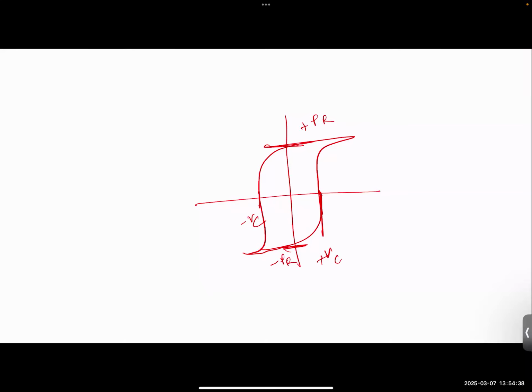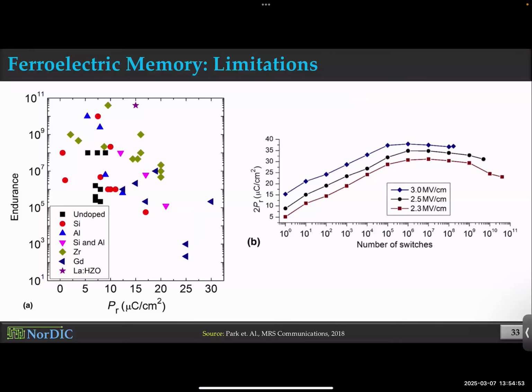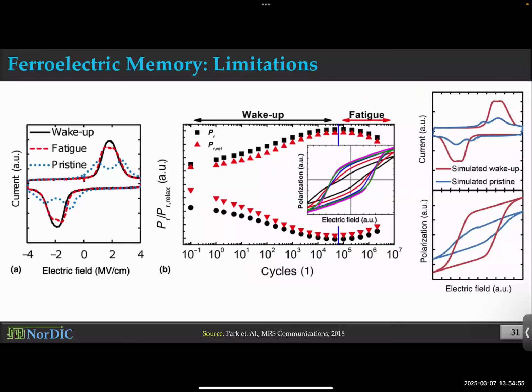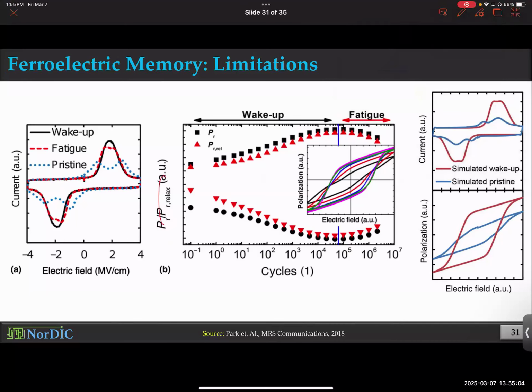Polarization? You guys all okay with that? Sure. Because we use positive and negative polarization to represent 0 and 1. So the farther the difference is, the better it should be in terms of memory stability, right? And reliable sensing. So having that idea in mind, consider a plot of remnant polarization. Basically this plot is normalized with respect to regular polarization, but don't worry about it. Consider that this is remnant polarization. And these are real data, as you can see, right?